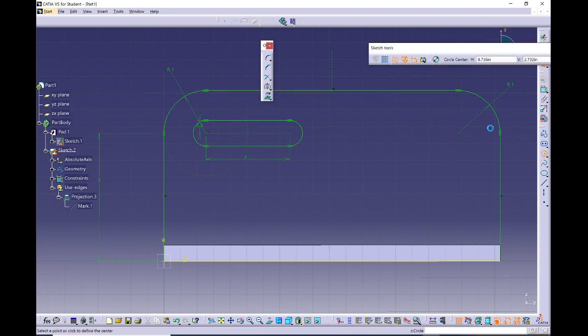Now, one thing you will forget is to turn this back to a regular, solid line. If I create another element, let's say I randomly create a circle, and you're wondering, hey, why is this construction? Well, you forgot to turn off construction. Let me delete this and turn off construction. You're going to constantly be clicking on this back and forth if you're using a lot of supporting geometry. Same thing with this line. This is a construction element. It's not part of the sketch, but it helps us generate this slot. If we were to delete this, then we would lose some of our constraints.